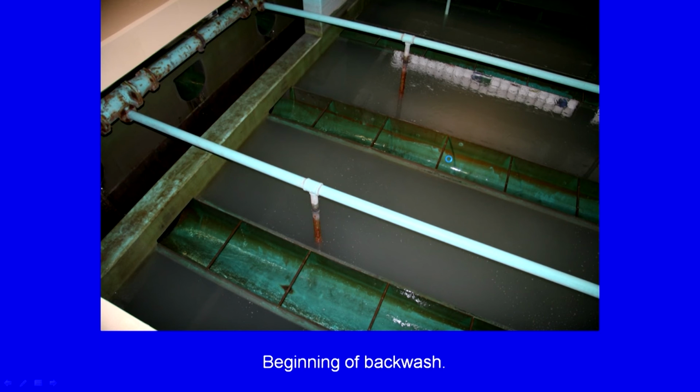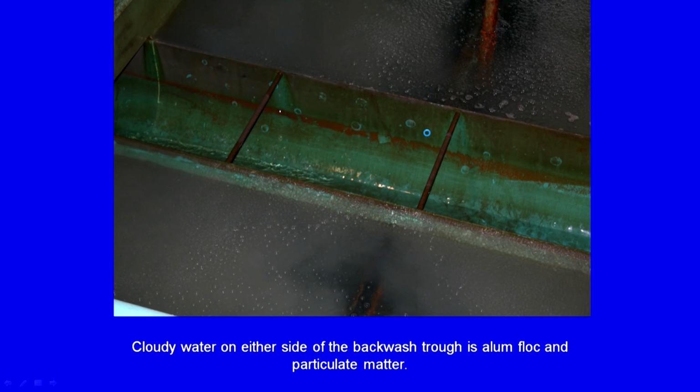Here they are going to begin backwashing. These are the backwash troughs. They are just about to start backwashing and this is where you have the relevant filtration occurring, but they just started pumping water in the reverse direction, I guess. So, water is going to come out from here and be collected in these backwash troughs. So, cloudy water on either side of the backwash trough.